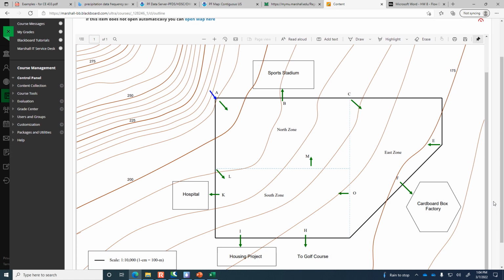I'm going to go through your demand estimation as quickly as I can and give you feedback, but you can begin your design based on the flow rates that you've got now. And then you may need to further change some of the pipes if I find a significant error in your methodology for the demand estimation. So you know the flow rate, and we just have to figure out, number 1, where should the pipes go? And your objective is to minimize the cost. And so it would be foolish, for example, if you had a separate pipe coming from location A to each one of these arrows. Think about what that would look like.